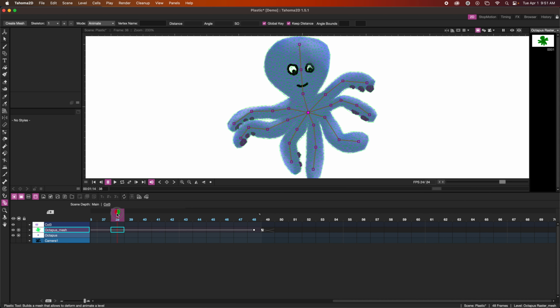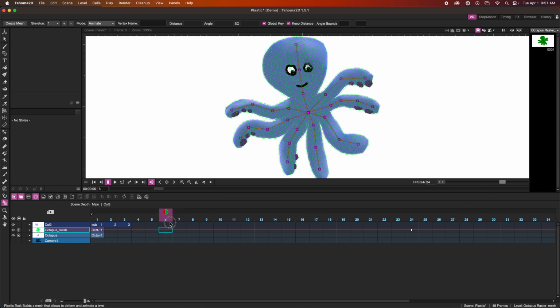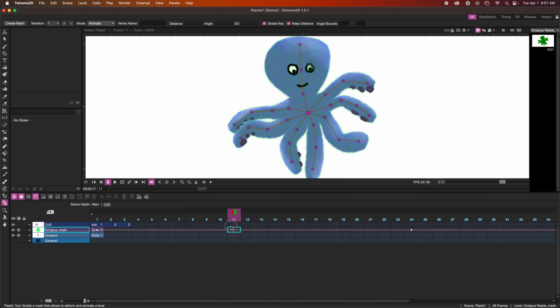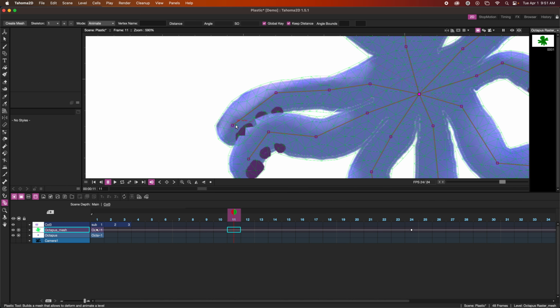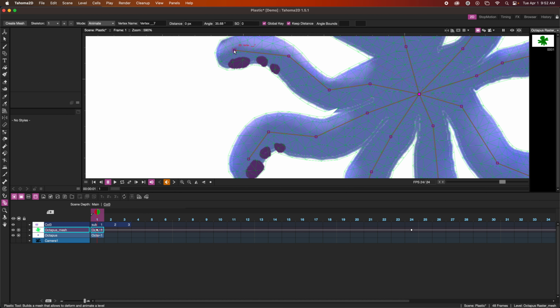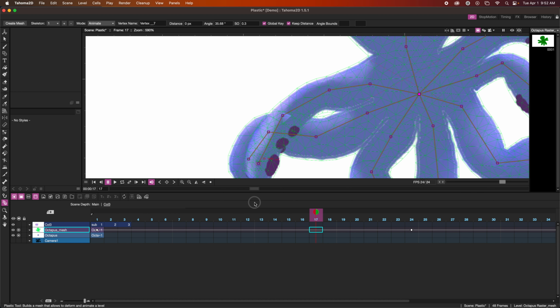All right, now something else that's pretty cool is we can actually control the stacking order. So over here, you can see that the order's getting a little bit wonky where the meshes are overlapping. So I can fix that and have more control over how it's going to behave. So maybe at the start here, this particular node has a stacking order of 1. So if I change that number, now that's moving in front.